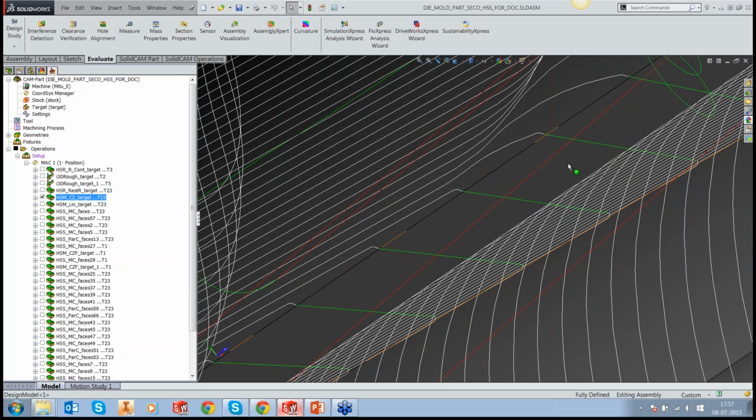In doing so, it actually slightly rubs on the wall, on the floor below. Although it's leaving material, in some cases, if the tool has been loaded too much, then it can actually dig into your wall in a very tight space. I'm talking of very tight space. If it's not a tight space, then it doesn't matter. It won't make that issue. So in a tight space, when it's trying to do this, you could see scratch-like marks coming on the floor.